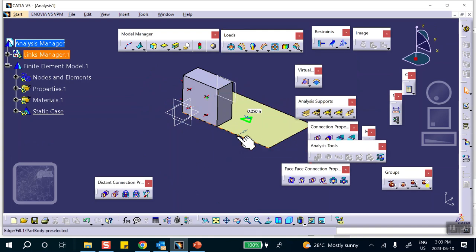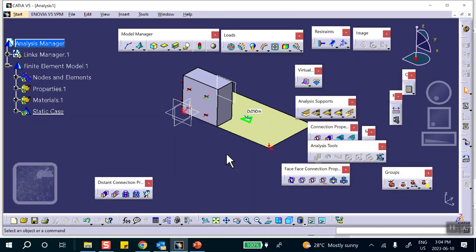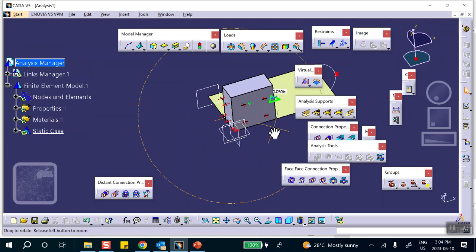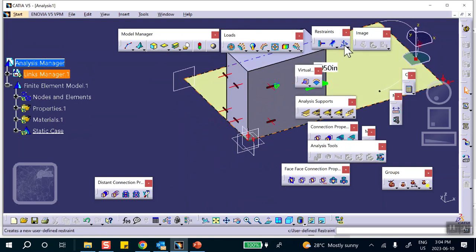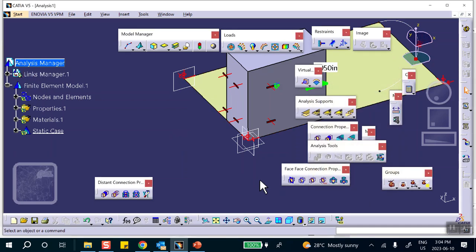These edges, this edge entirely sits in the XZ plane of the system. XZ plane, you can see that. So there is no displacement in Y, rotation is exactly opposite. Good. And this other edge, let's uncheck all of these. This other edge sits in the YZ plane, no displacement in X, rotations exactly the opposite. That takes care of symmetry.